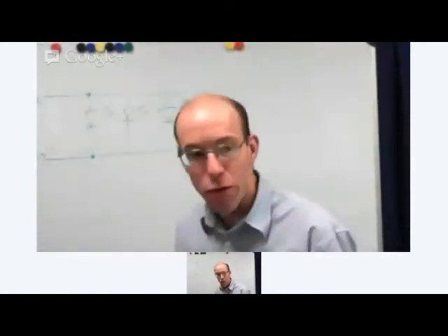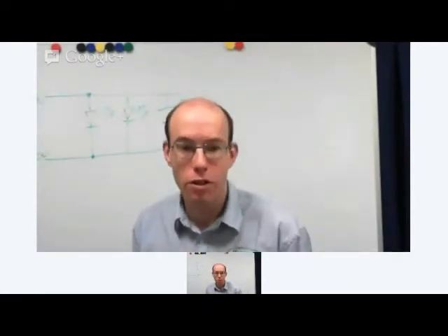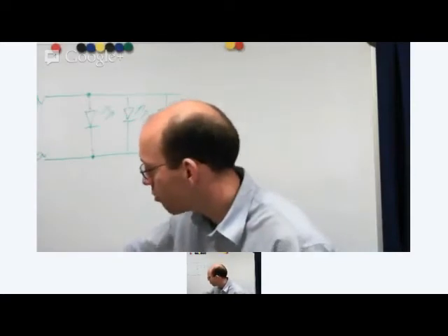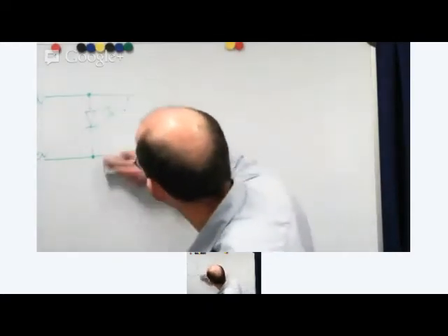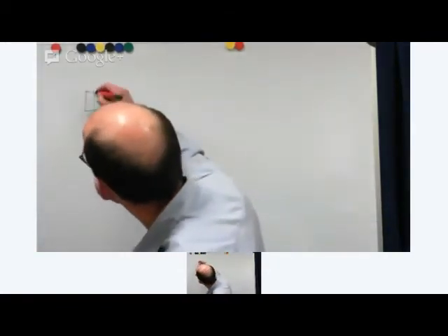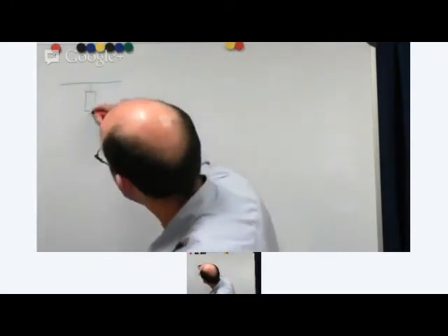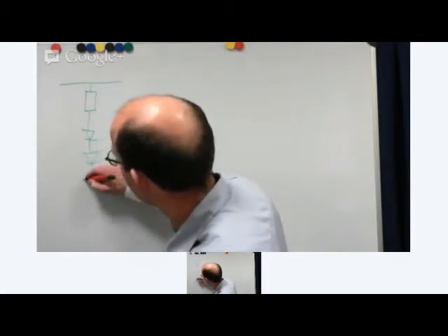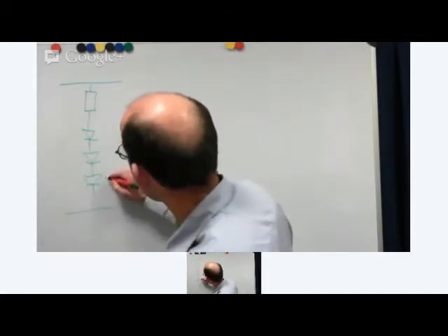For normal LEDs, we can do 2 different connections. We can either do a series connection, or we can do a parallel connection. So suppose we had 3 white LEDs and we wanted to do a series connection on the LEDs. We can share one current limit resistor, and we can put a number of LEDs off the same supply like that.